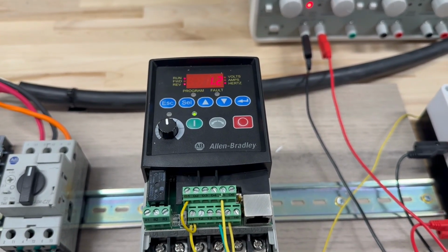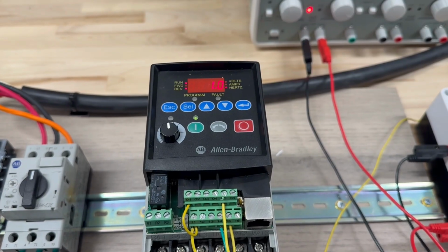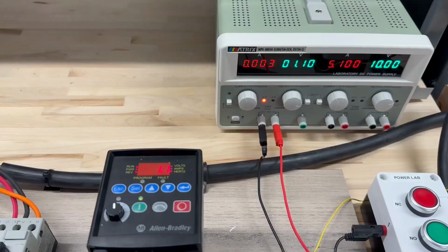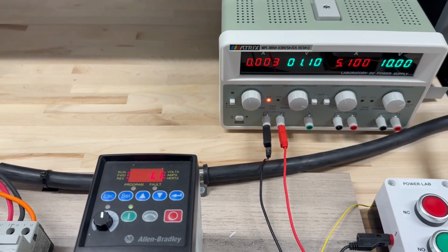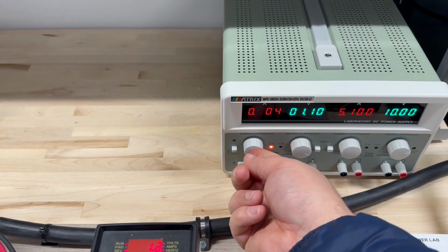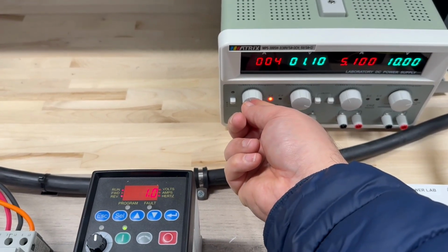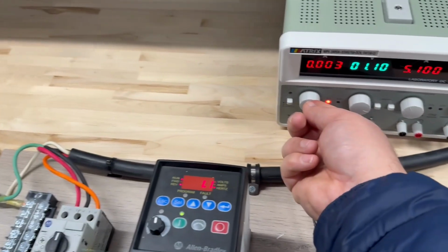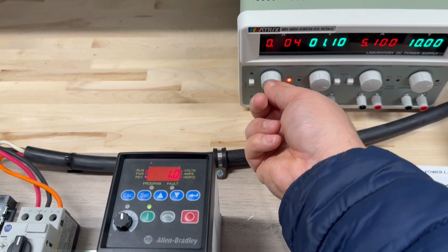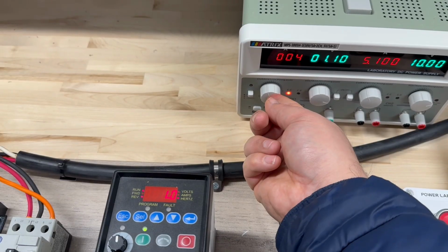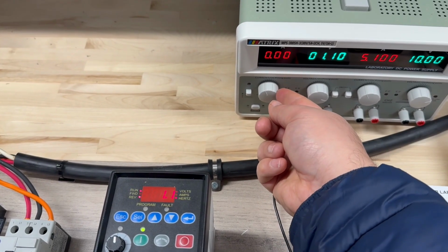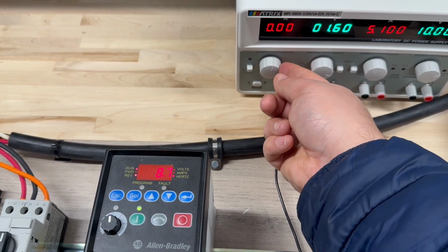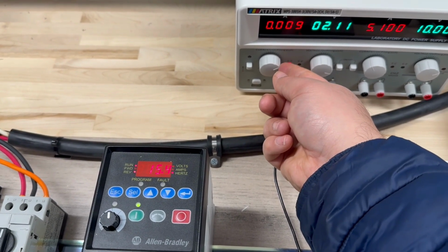So see, it is actually 0.004 or 4 milliamp. It's almost around 0. What you expect is to increase that, and the frequency goes up and the motor runs faster, right? So this is what we need to do. It would be good to have all 3 in the same frame, which is difficult, so let's just have the frequency and this current in the same frame. So see, now increase to 5, frequency goes up, go to 6, frequency goes up, 7, 8, 9.